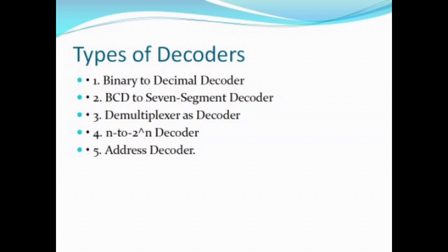The BCD to 7 segment decoder converts the 4-bit BCD input to 7 individual segment signals. That is, it converts binary coded inputs into signals to drive display segments. It is mainly used in digital clocks, calculators, and output control. It's also used in LED and LCD displays, mainly 7 segment displays. A common IC used as a BCD to 7 segment decoder is the 7447.